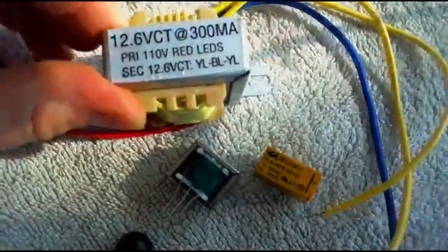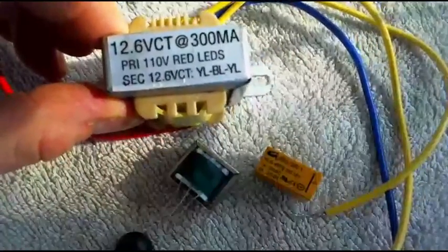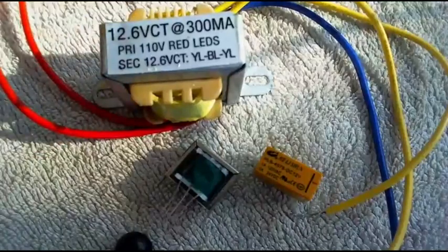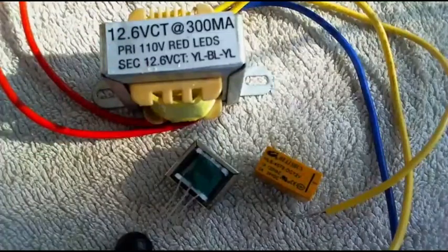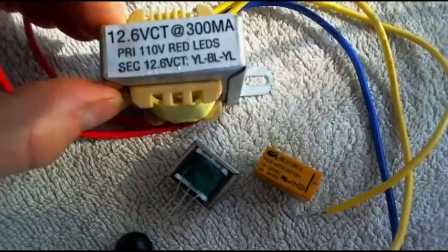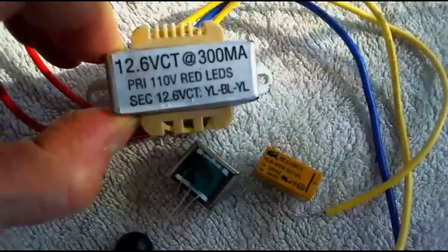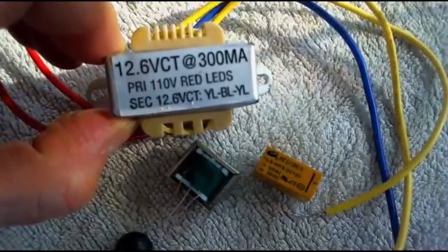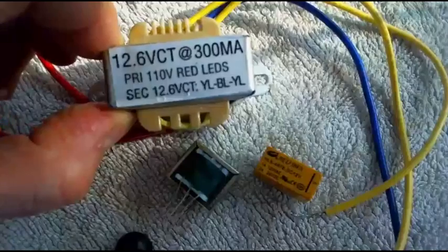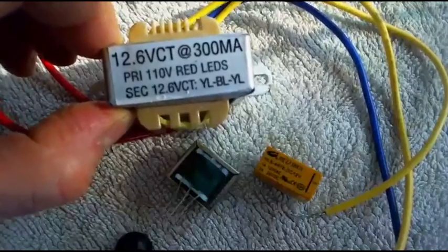So when we talk about windings on a transformer, each winding is nothing more than an inductor, and depending on the diameter of the coil, the length of the coil, the number of wraps, that will determine its inductance. So we don't know what those are, but we can use resonance with a known capacitor value and a sweep of applied frequencies to effectively measure inductance.